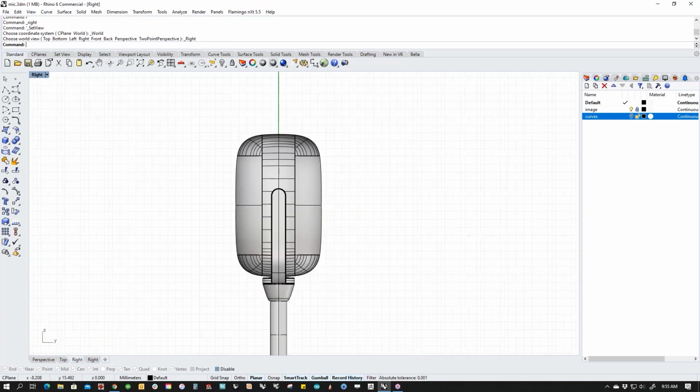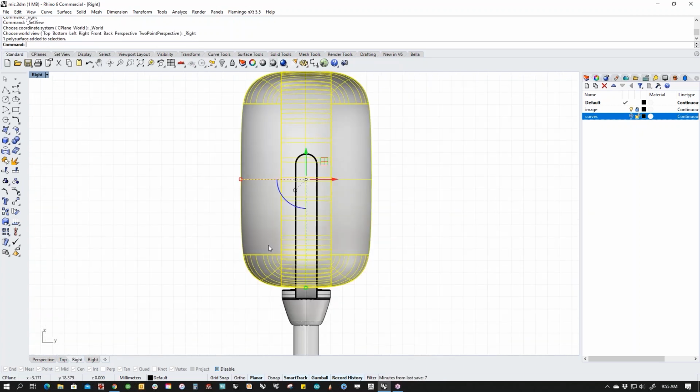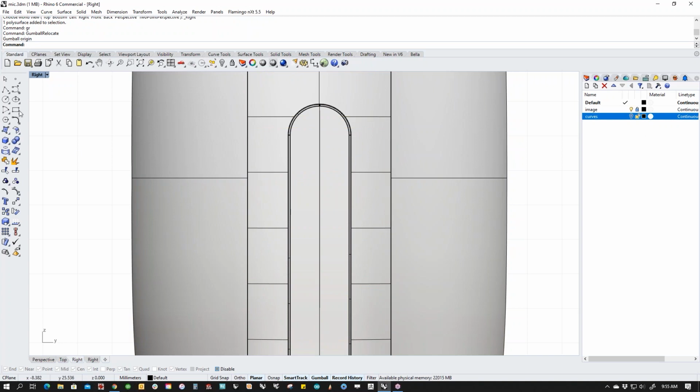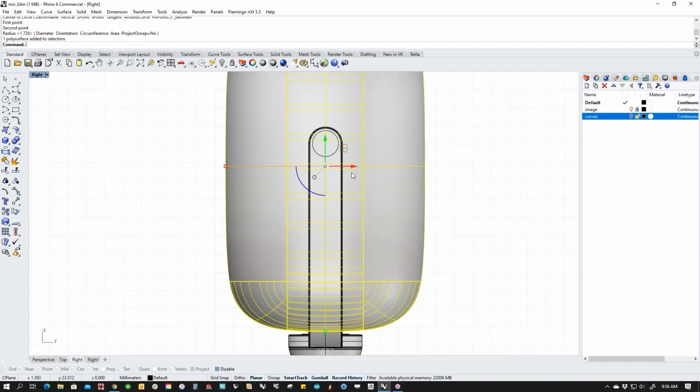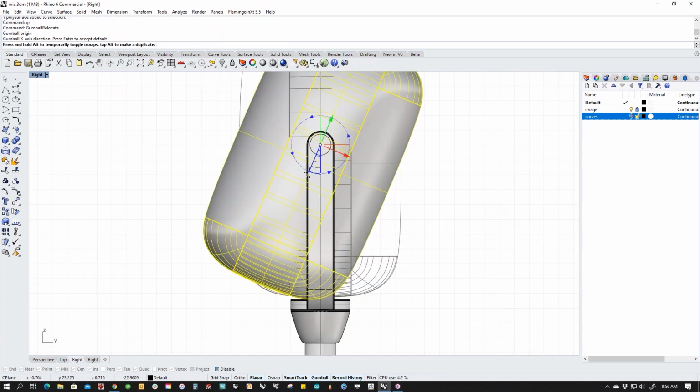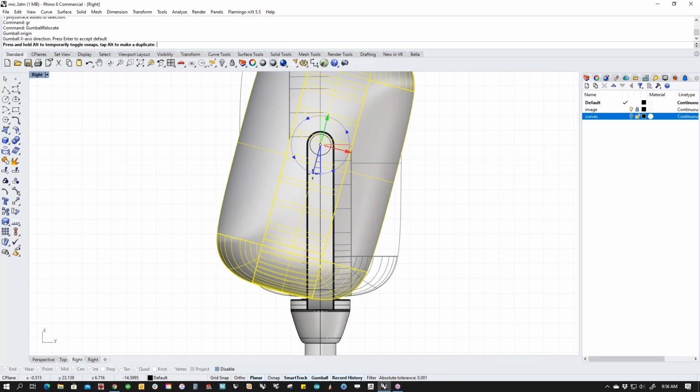Now, if we're really being fussy, we should look and we should set our gumball to the center of our pivot and make sure that this thing actually does rotate. And I'm using the between snap again to snap this right in the center there. So that'll be our center. So let's set our gumball to there. And then let's rotate it and make sure it doesn't smack into there. And it kind of does just a little bit. See that?